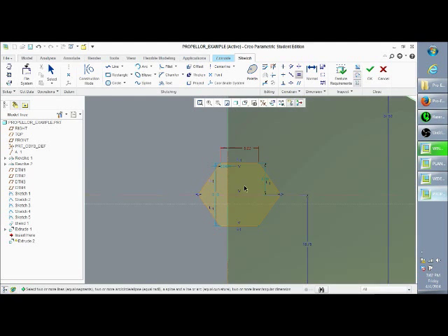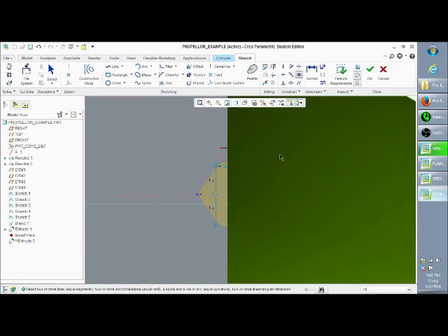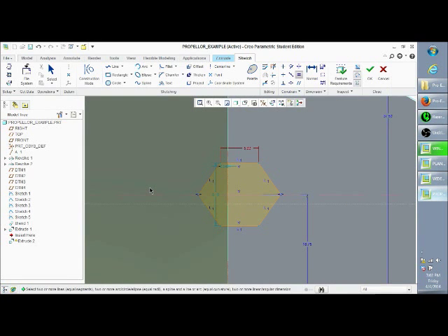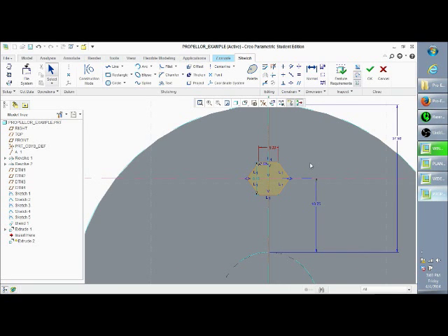Top line. Bottom line. Again, same dimension. And the same for this last line. It'll automatically set it up. You notice how before it had all these degrees right here? Now you don't need to manually edit them because, using geometry, it'll automatically set it up. So notice that here it's not in the middle, so we can manually set this to 5 divided by 2 so that it's aligned there in the middle. And there we go, we have the shape that we want.